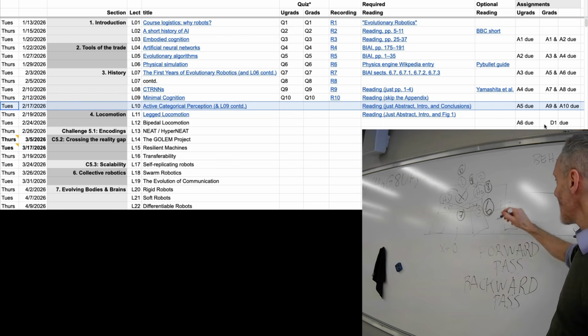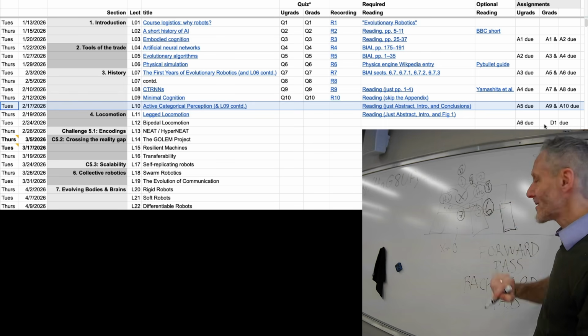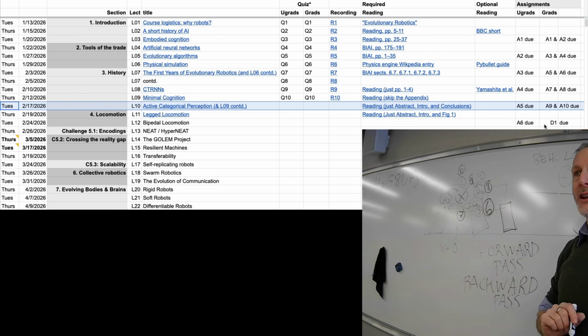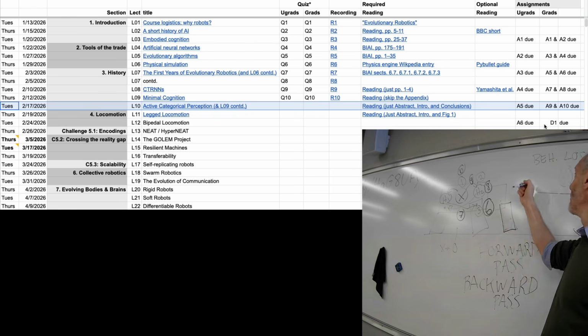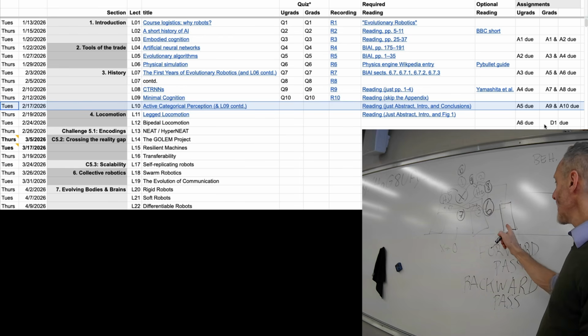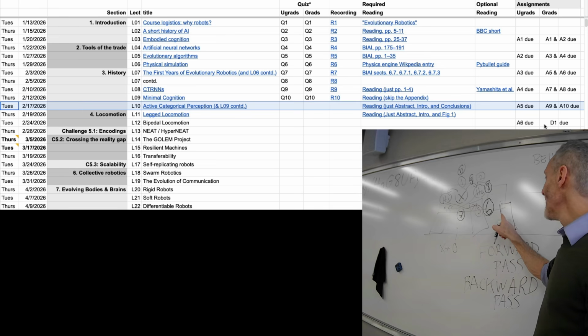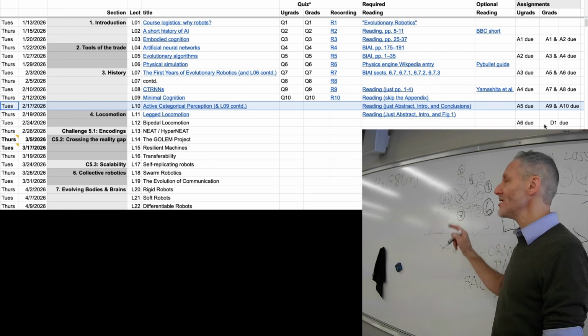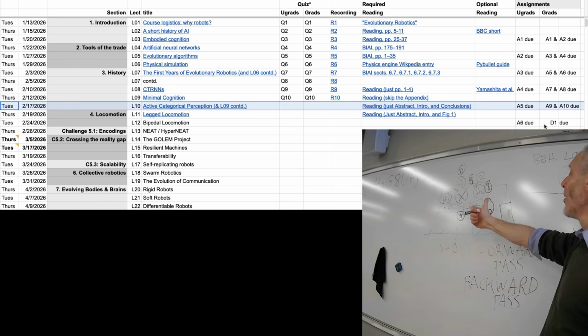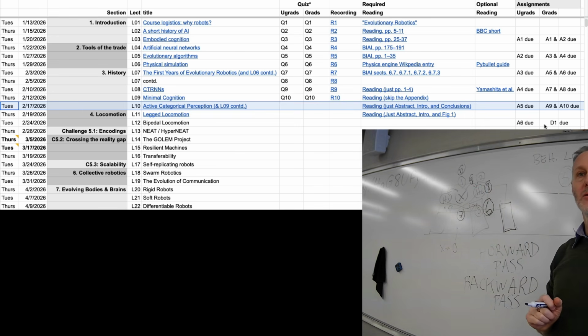Perhaps gradient descent says the mass of the front leg, remember F equals ma, M stands for mass, the mass is also to blame for a non-zero behavioral loss. The differentiable simulator will allow gradient descent to tell you if the mass of this leg had been a little bit less or a little bit more, the robot, given all of these synaptic weights and given this brain, would have traveled further to the right.